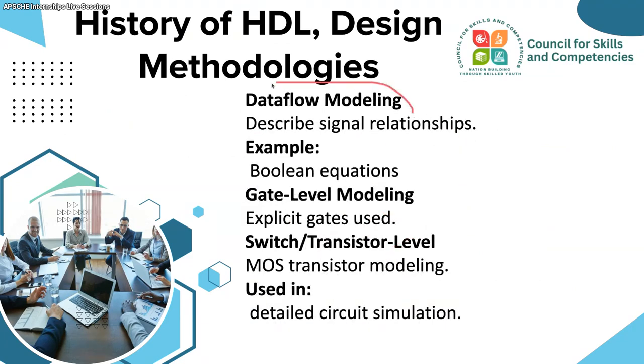Next is data flow modeling. Here, how the data is going to flow is described. It describes the signal relationships, for example Boolean equations. That is data flow modeling. Next, gate level modeling: what gates it is going to use. I am talking about the abstraction levels of HDL, hardware description language.